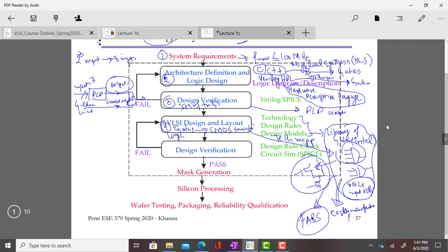One are logic gates, they do not have anything to do with manufacturability, and the other are library gates, which is what you can manufacture. So this technology mapping is about mapping logic gates to library gates.